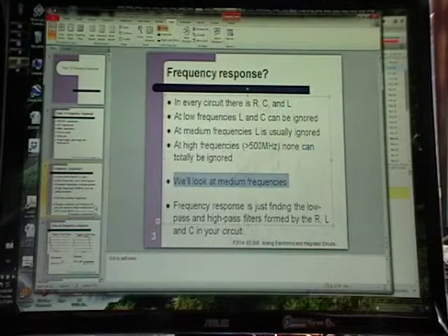When you work out the capacitances, say the gate-source capacitance for a MOSFET, you see that it is so small that any pole or zero it causes is way out at a really high frequency.